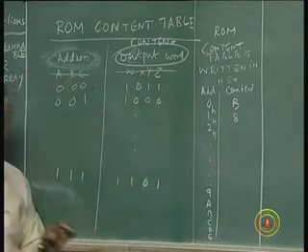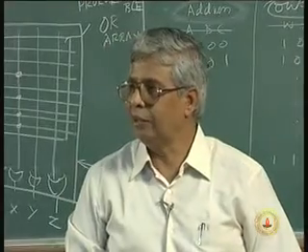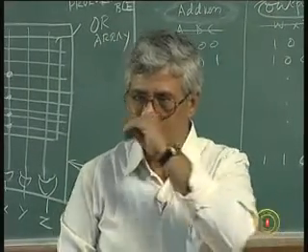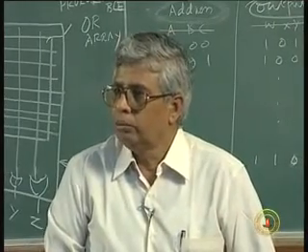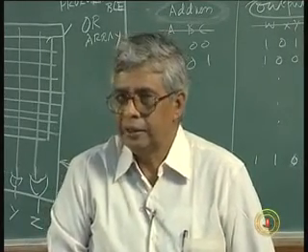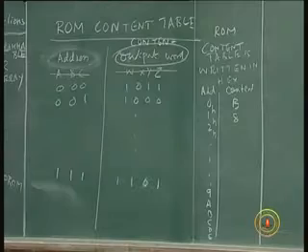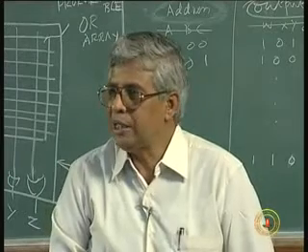So I'll give you an exercise now. Remember that 4-bit BCD to 7-segment converter, decoder, we did earlier? Take it and put it in a ROM. Get a ROM content table for that exercise. Don't make it BCD, make it binary.